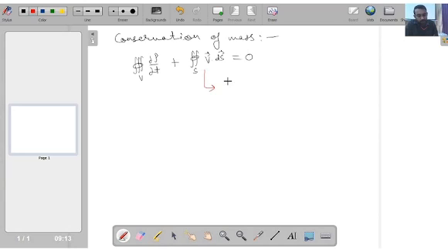Now particularly this term over here, using the Gauss divergence theorem, this surface integral can be converted into a volume integral. So if we do so, sorry, one mistake I have made, it should be rho v vector dot ds. Now the first term has a volume integral, so another issue is it should have an integral over v bar also. Okay, so the first term is in volume integral. What I want is my entire equation in the volume integral. So for the second term also I will try to convert it into the volume integral.